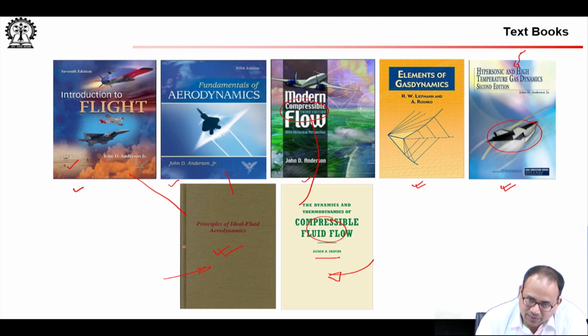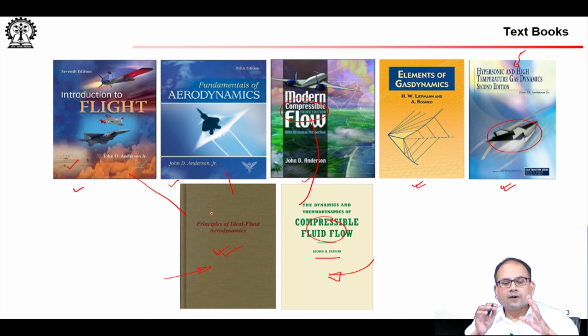Again, like the fundamental aspects of fluid mechanics as well, such as why the curl of the velocity field gives you vorticity, how circulation relates to vorticity, and how circulation relates to lift. Those things are nicely considered in these books. Also, while we talk about how airfoils are designed, you will see that there is something called conformal mapping and something known as the Zhukovsky transformation. It is a little mathematically involved, but Karamcheti's book gives you a nice insight into that kind of transformation.